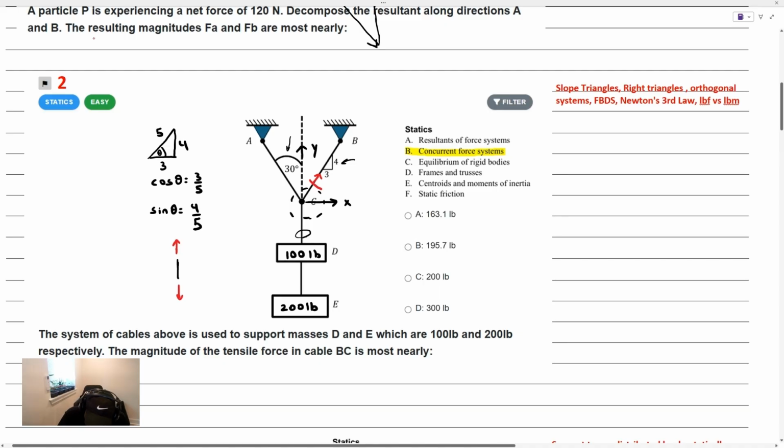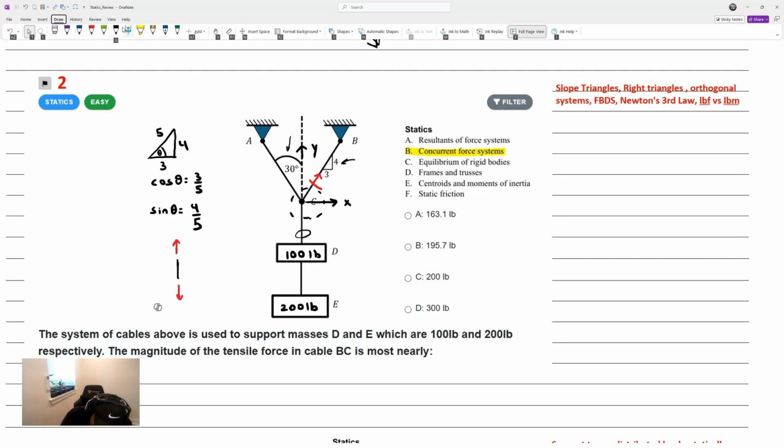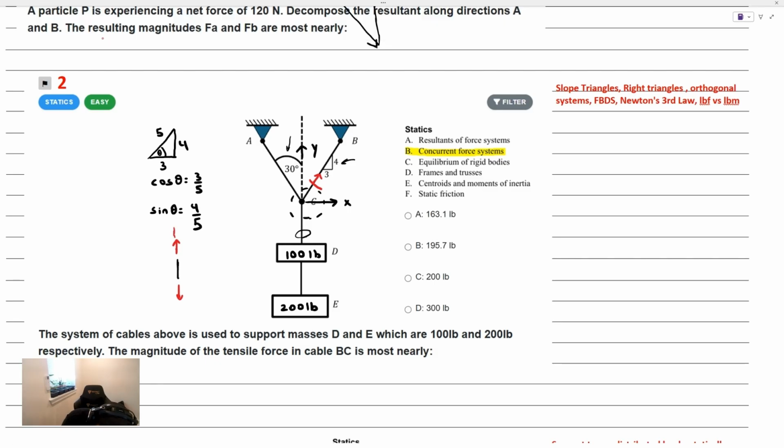By Newton's third law, we know the force at that joint is going to be pointing downwards here, and this would be the joint C. Those equal and opposite forces, when you overlay them back at point C, you would see them become self-canceling. So that's why forces pointing away from the joint are always in tension, right? We draw a nice clean free body diagram here.